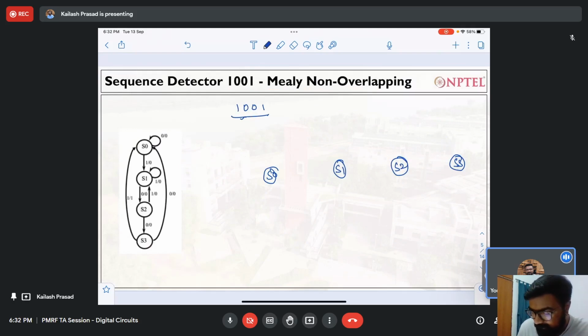So I am at my initial state, right? If I get a 1, I will go to here, right? So this is my 1. Has my sequence been completed? The answer is no, because I have only detected 1 up to here. So I will give my output 0. So please note that this is my input, this is my output. Okay. If I get an input 1, I will go to the next state. The state has changed, but the output remains 0, right?